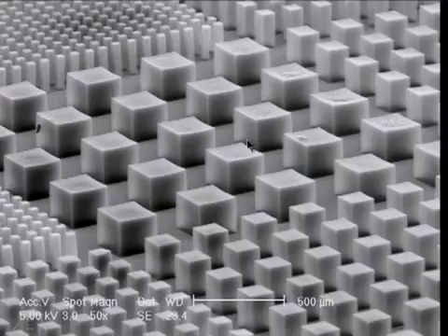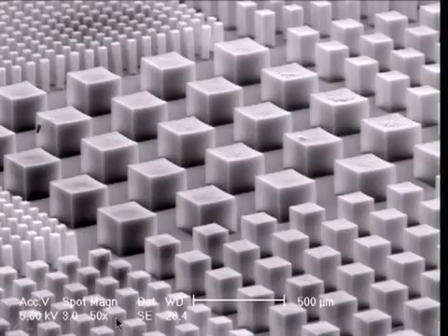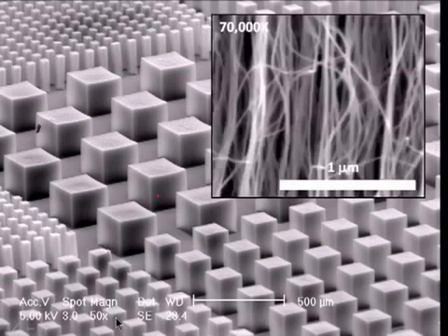You could take an image with this magnification, 50x, using an optical microscope, but you wouldn't have the type of resolution of the texture and also the depth of field. And I think, to me, that's also one of the useful aspects of an SEM, that you get a fairly large depth of field. Everything in here, to a certain extent, looks pretty much in focus, although this is tilted at about 45 degrees and we're looking deep across it. And it was expressed on the previous slide with the specifications. We can go down to nanometers, and this is a picture of the forest as you zoom in. I made this little dot, which is still way larger than the dot would be in reality.